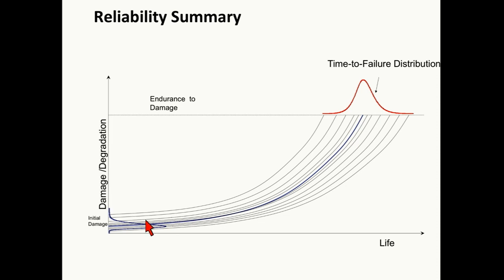Later on, we developed the physics of failure, finding some initial damage and growing that damage based on these physics models to find how the damage is accumulated for each failure mechanism, and instead finding these times of failure based on these physics models, until this damage reaches a given endurance or capacity of the system to fail. And of course, even this capacity is measured by testing.